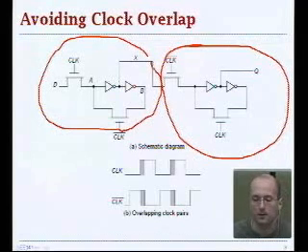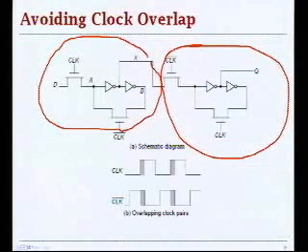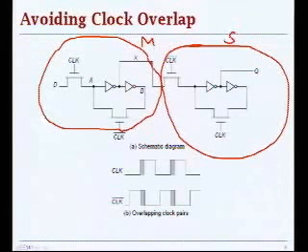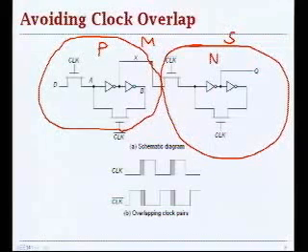Positive, right? So this is a positive latch. Now what you have here is a master-slave configuration. One is a positive latch and another is a negative latch. So this is positive, this is negative. And therefore, when you cascade positive and negative latch, you effectively have sampling at the falling edge, because the edge of the slave latch is what really determines your sampling.